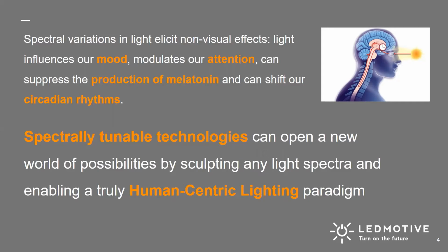The non-visual pathway begins in the intrinsically photosensitive retinal ganglion cells located in our eye, which contain melanopsin, a photopigment directly responsive to light. Melanopsin spectral sensitivity peaks at 480 nanometers in the short wavelength region, blue, and these signals from the ipRGCs ultimately affect our circadian rhythms, body temperature, attention, sleep, heart rate, brain performance, and more. And also they interact with the classical visual pathway in ways that we do not yet understand. So when designing lighting spaces, it is important to consider the non-visual effects of light, and that means the melanopic lux, and that the whole spectral shape of light are key.